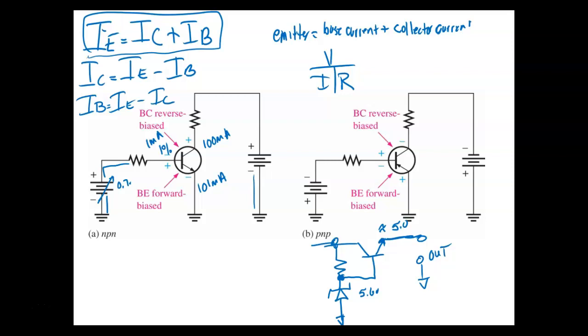Because what can we get out of a transistor? We get current gain, but I can take that current gain and run it through a resistor and get voltage gains, right? You understand? By adding a fixed resistor. So here we're taking this little bit of current right there, right? You understand? And so if this thing had a beta of 300, then that means if I'm putting 1 milliamp over here, I could get what? 300 milliamps over there on my output. And we've got something else we can do to really get the gain way up.